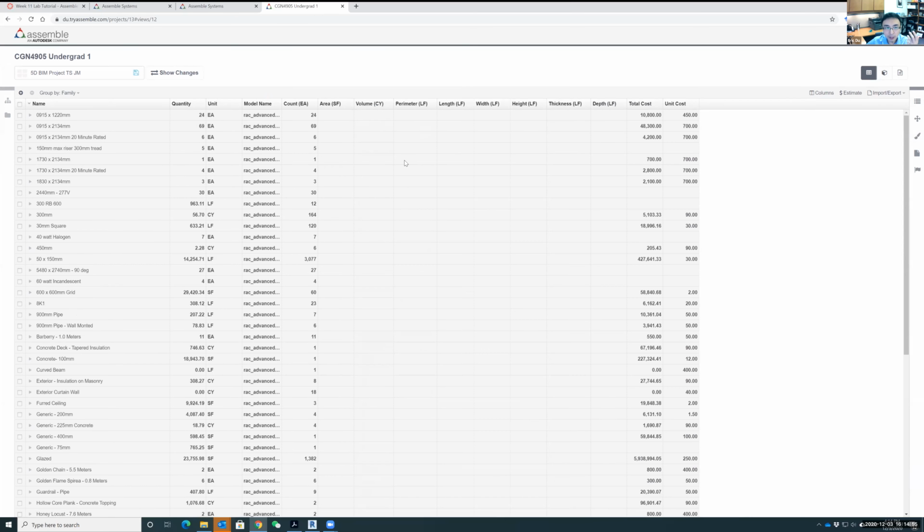And a cool function, which is something we are going to learn, is how to perform a quick cost estimate with the assembly system. So first, we need to switch this filter to, sorry. We need to switch this filter to assembly code like this, since this is a cost coding system. And we need to somehow input the unit price somewhere.